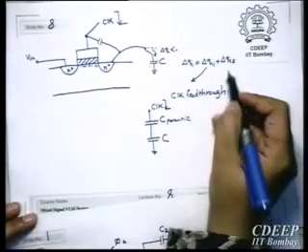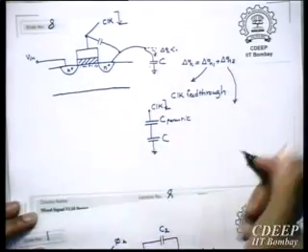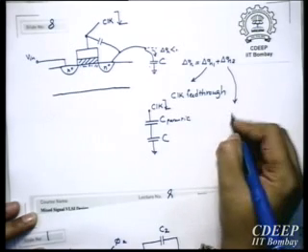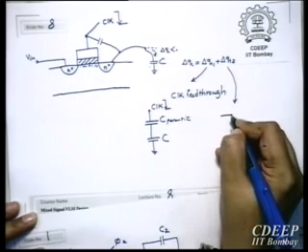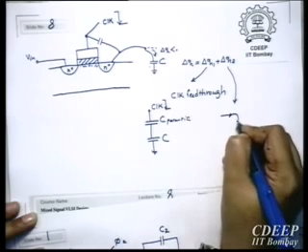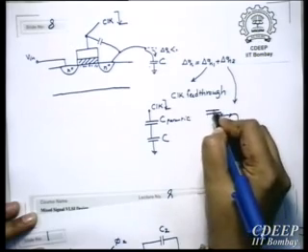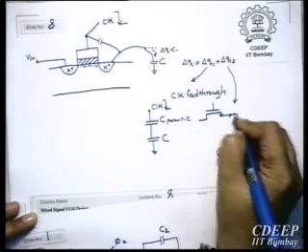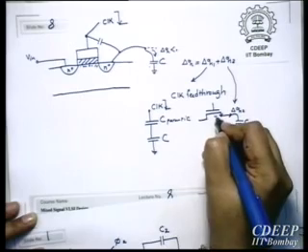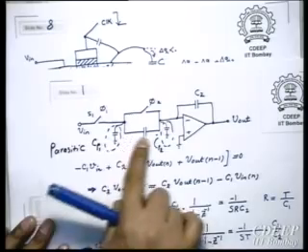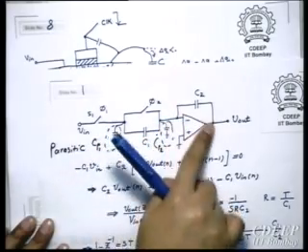And delta Q2 is because when the switch is getting off, some part of the channel charge, you can look at it as a distributed RC, will come to this capacitor C, which is connected to the source. So this delta Q2 is the charge which was stored in the channel when the transistor goes from on to off. Therefore, these two will change the charge which was here as well as here, and therefore we will have a change in output voltage.